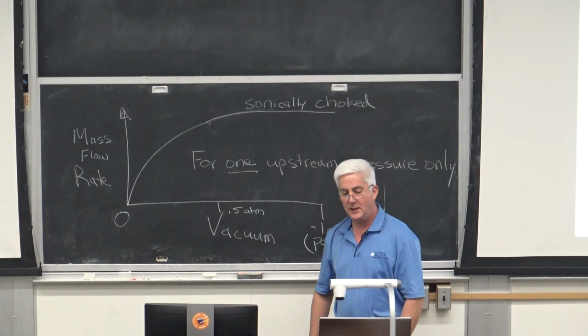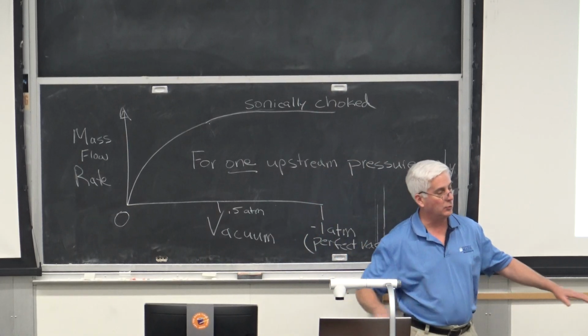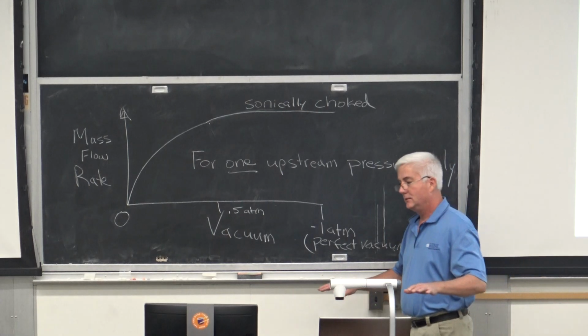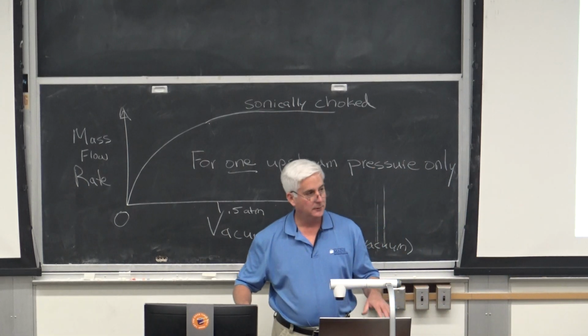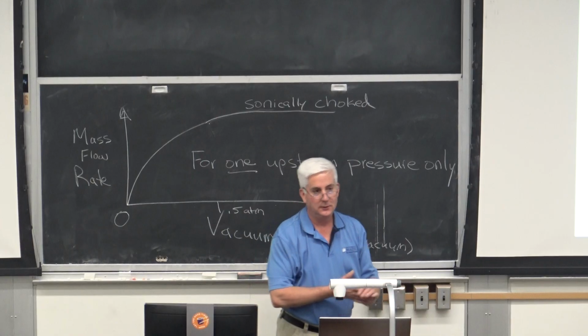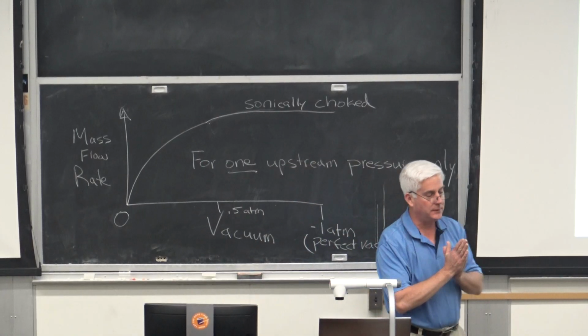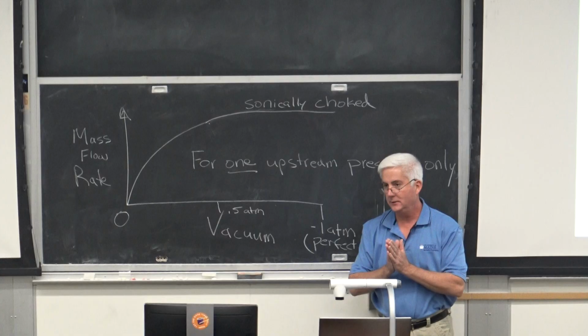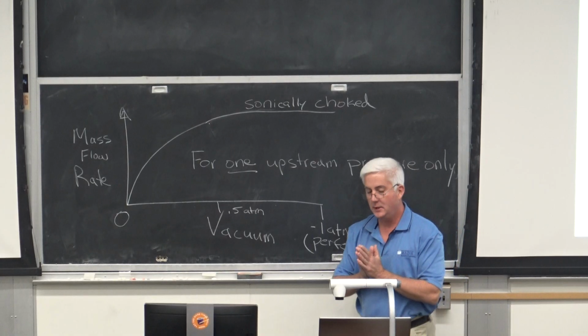So implicit in that is when you're in nice warm air down here at the ground, the speed of sound is pretty fast. You go up high, 35,000 feet where it's 65 below zero Fahrenheit, your speed of sound slows down.